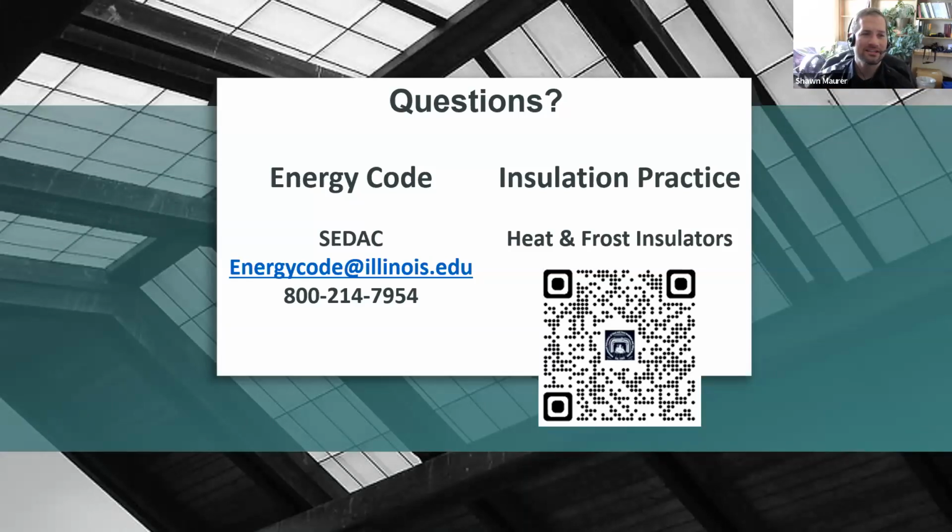Another comment here: in cold climates, it's better to have a separate stud wall or chase for piping that is interior to the insulated exterior wall. That is true in most situations, but as energy codes are allowing, almost requiring more and more now, continuous insulation to the outside of the wall cavity, that can offset the need to build those interior stud wall chases. If you load up on that exterior continuous insulation, number one, it reduces how much insulation you have to install to get the same performance factor, and it can open up those cavities where now it's easier to do maintenance and run plumbing, wiring, all that other stuff in those stud wall cavities.